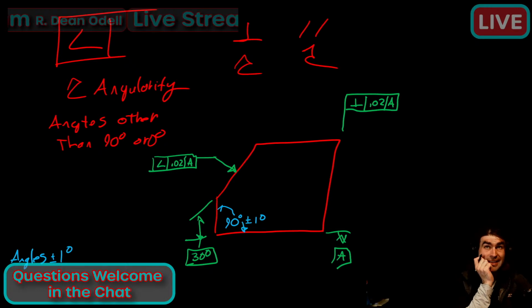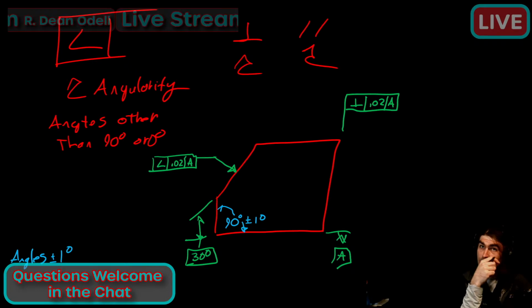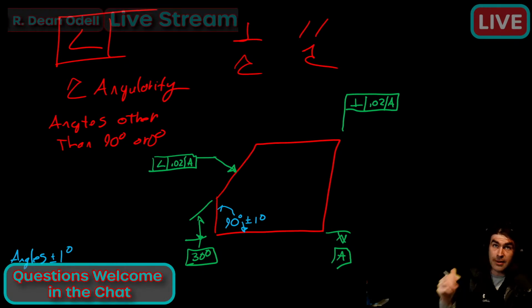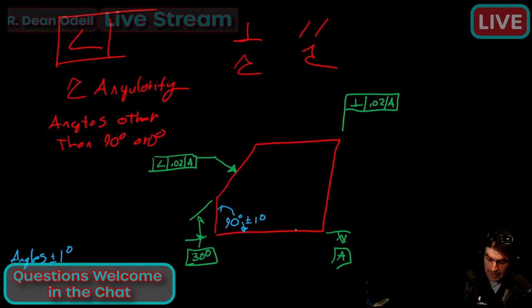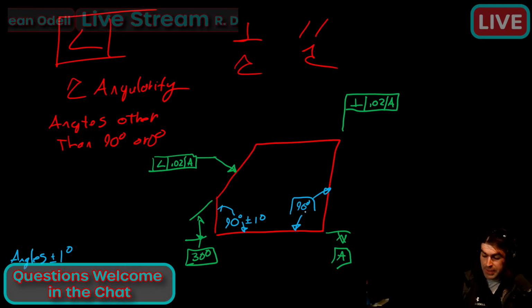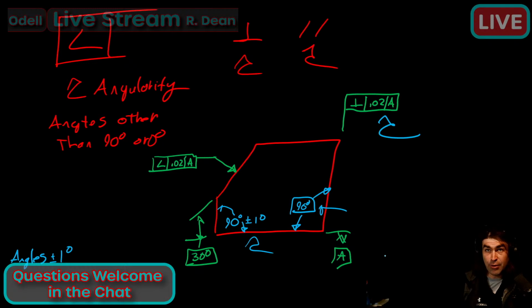Does that get checked? Probably not that often. Probably only when something doesn't work. That kind of thing would get checked, but it's there, whether you like it or not. Now, what happens with orientation tolerances is that 90-degree angle is hanging out there, but it becomes basic. This plus or minus 1 degree does not apply to this. This orientation tolerance takes over.